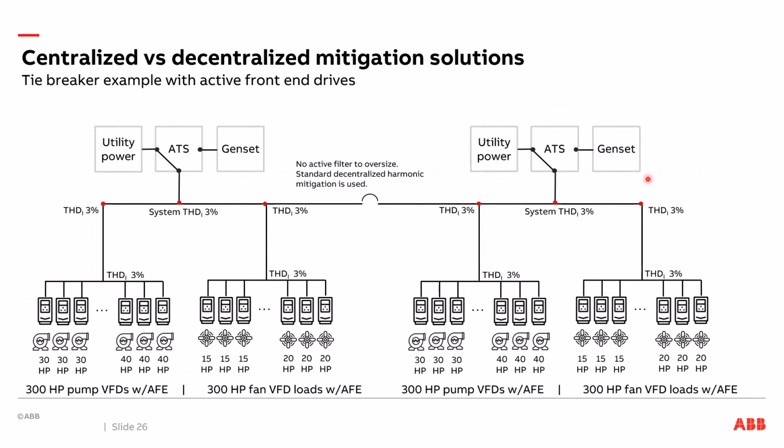Now we'll look at the example, same thing, but instead I have active front end drives down here. So I've got the low harmonics in the first place. I'm not creating the harmonics. I have my normal system. It's this half over here, this half over here.